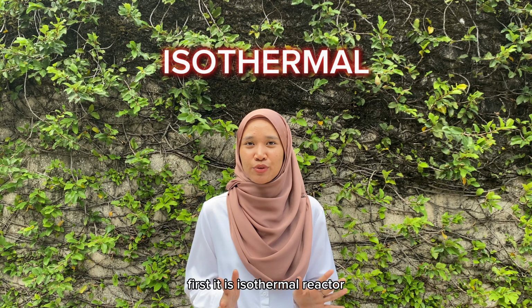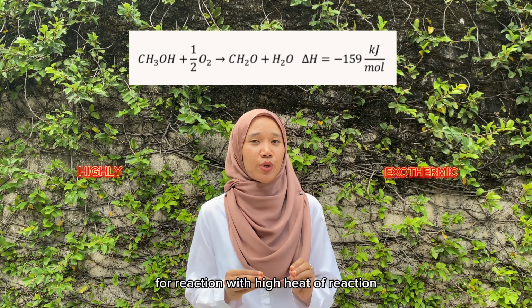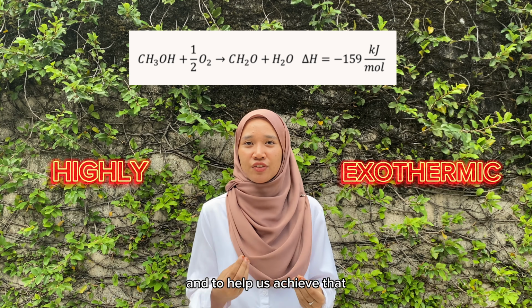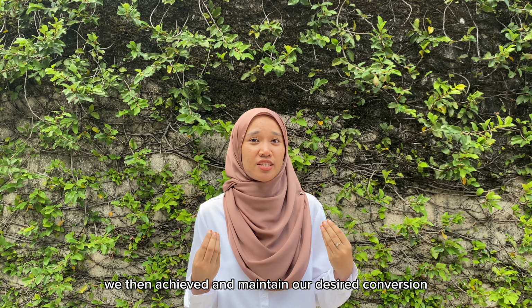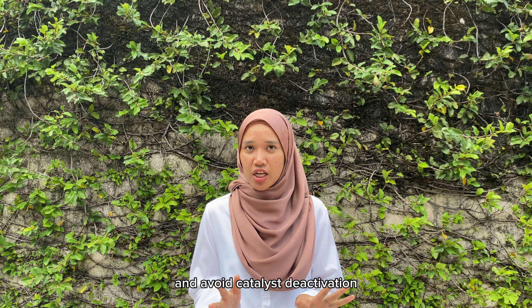First, it is an isothermal reactor, which is preferred for reactions with high heat of reaction, and to help us achieve that, we supply a continuous flow of cooling water. We then achieve and maintain our desired conversion and avoid catalyst deactivation.